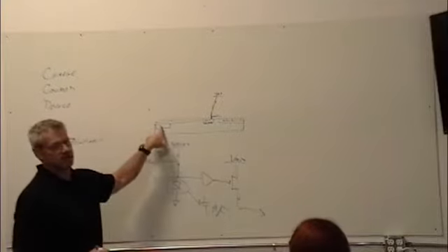You see sometimes a little smaller and sometimes a little bigger, whatever, but it's all designed with the optical train and everything else in mind. Because when you go smaller and smaller, you lose well capacity and a bunch of other things. But 6 to 15 micron pixels, if you're talking visible, 8 to 12 are what I used to see a lot of. And that stayed fairly constant over like 10, 15 years of time. So that's a sweet spot.